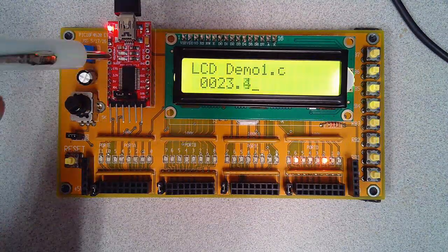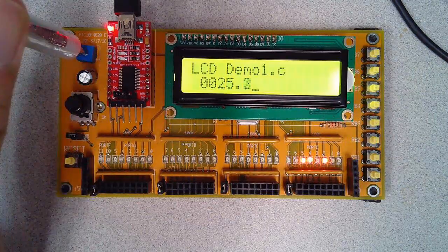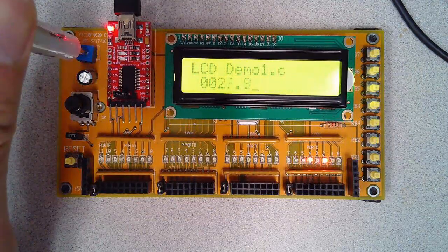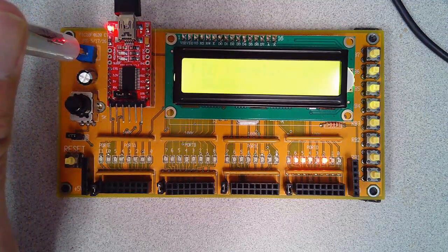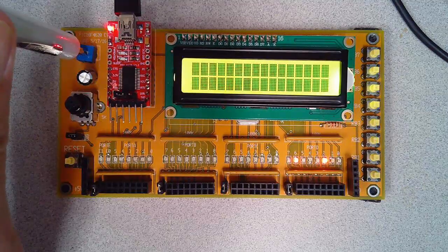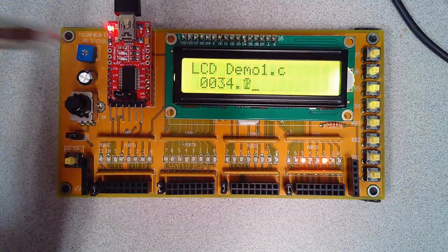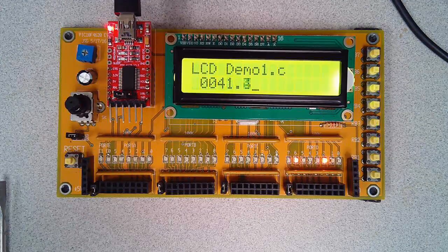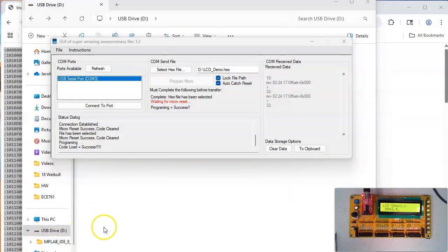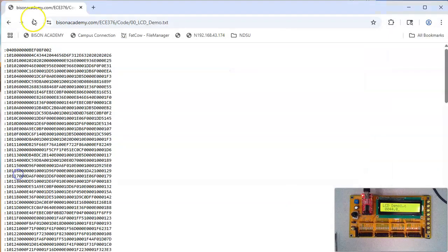And if your LCD display is blank, it's probably the contrast. That's this knob right here. As I turn it, this changes the contrast. Turn it until you can see a message. Right now, I see black dots. I get it just right, I can see a message on the display. If you have that message and it's counting and all your lights blink, you got a working board. In terms of other programs to download, we'll be talking about that throughout the semester.